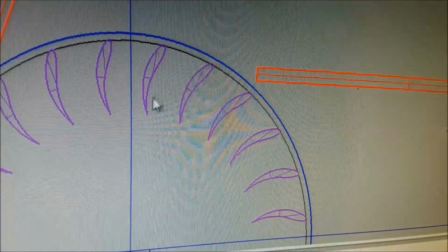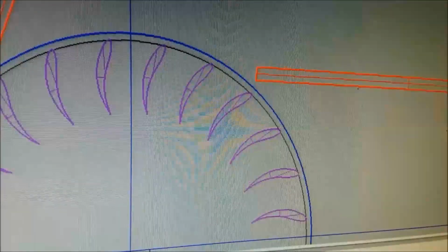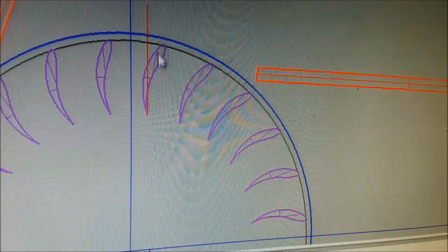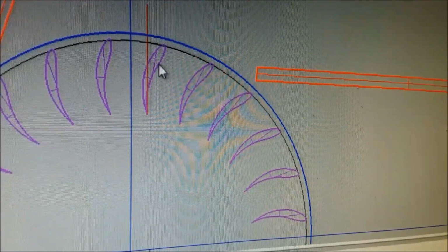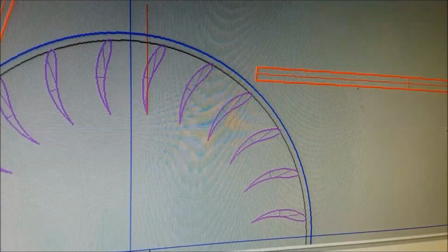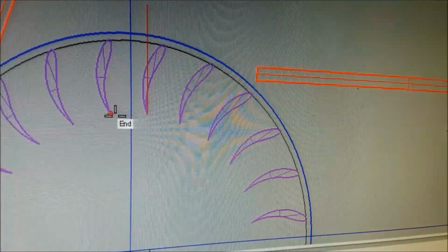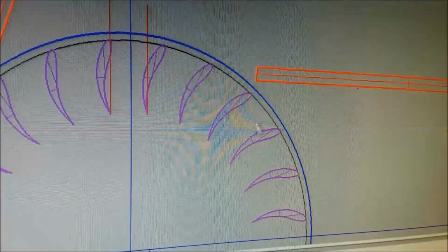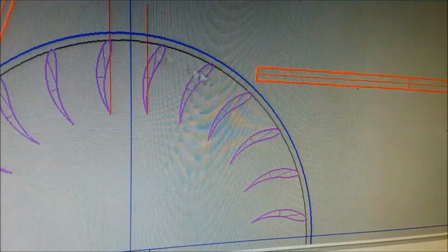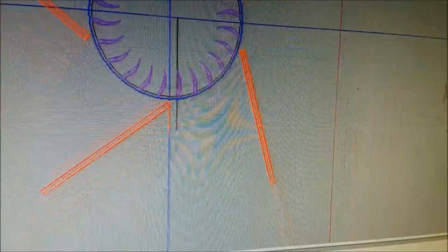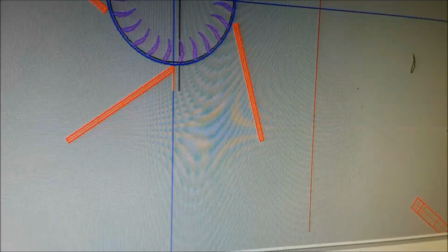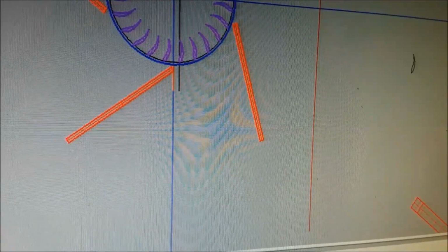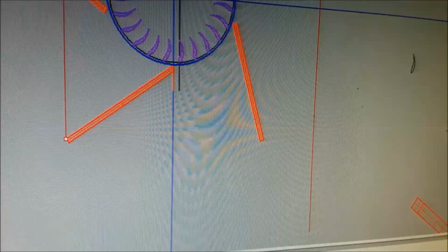So over to about here, about that much of the blade is going to see some air coming out. And then the next blade does nothing. So we're picking up air on half of the rotor down here. And we've blocked the air from coming through this side over here with the baffle, because this baffle is its worst case point.